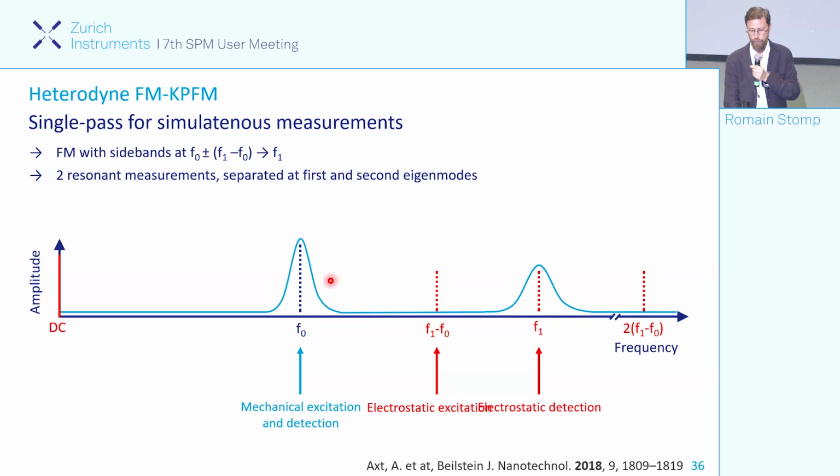And you send that directly to the amplitude of the second eigenmode. And of course, you are exactly again at the maximum amplification factor because you don't want to be sitting here or here. You want to be sitting at the maximum. The Q factor is a bit lower, the stiffness is a bit higher, but still you have a good measurement, and it's still a phase sensitive technique.